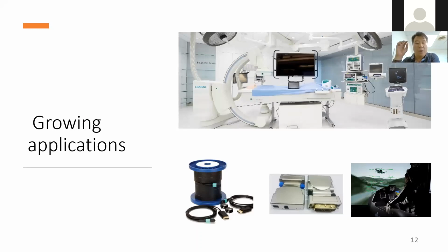So technically, this type of MPO, in this particular case that you saw, has 12 fibers built in. If you look at it, you're going to see 12 very small holes. So there are actually 12 fibers through that connector, but it's all within one cable jacket, right? I hope that answered the question. That allows you to send a lot of different information and different signals, because you have all these multiple fibers already built into the cable. Okay. All right. I hope that answered the question.